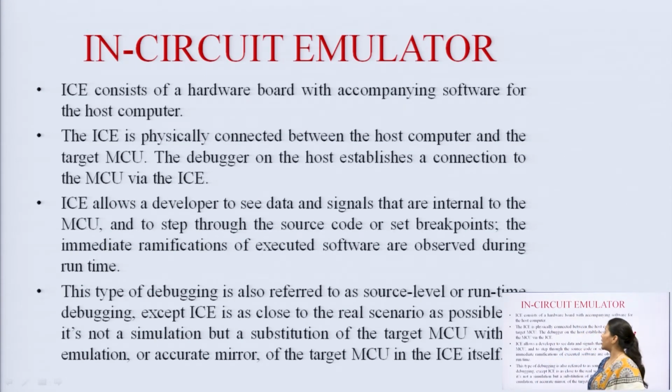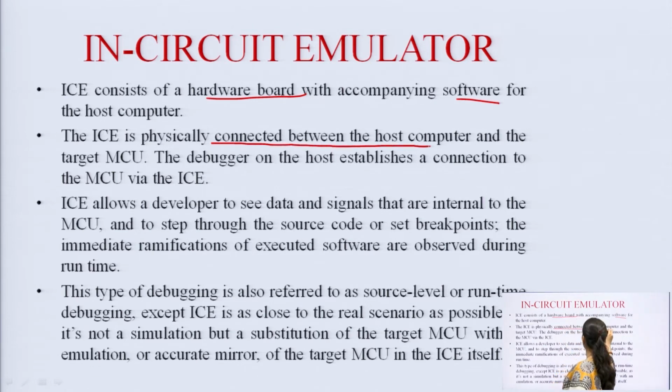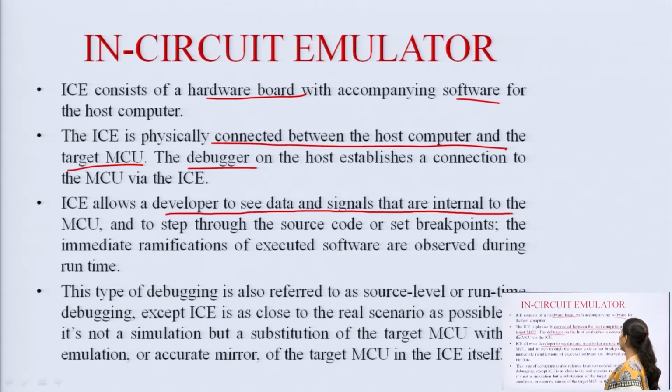It consists of a hardware board with accompanying software for the host computer. It is physically connected between the host computer and the target MCU. The debugger on the host establishes a connection to the MCU via the ICE. So, it allows a developer to see data and signals that are internal to the MCU. This is what we want to see, this is the thing we wanted to judge.